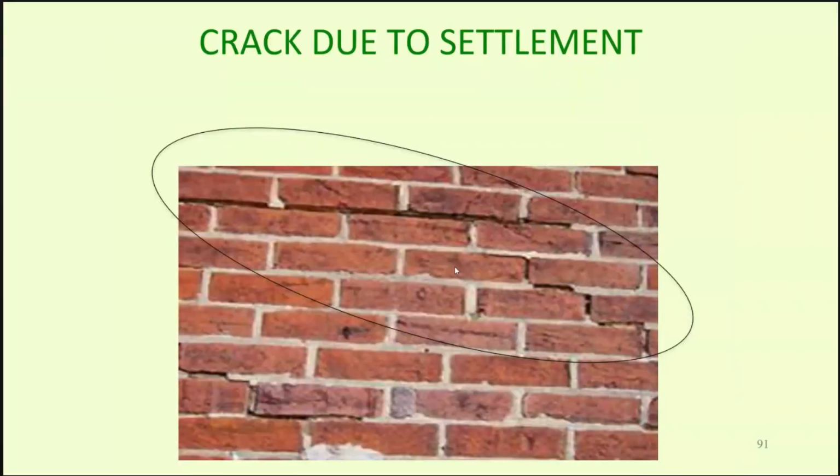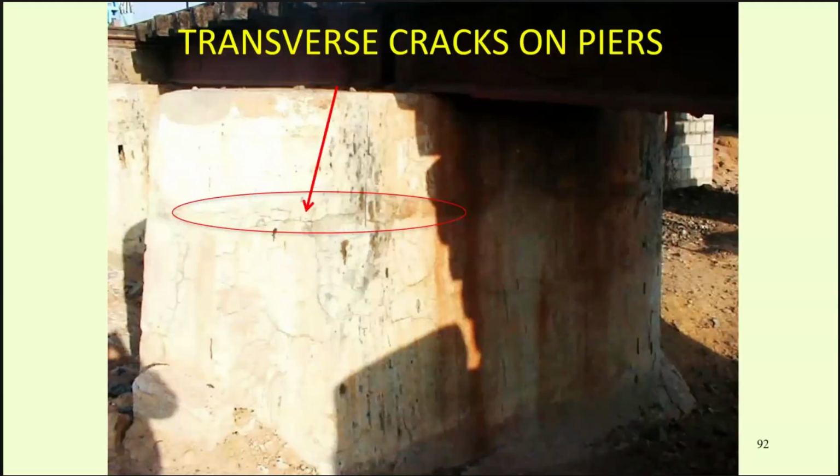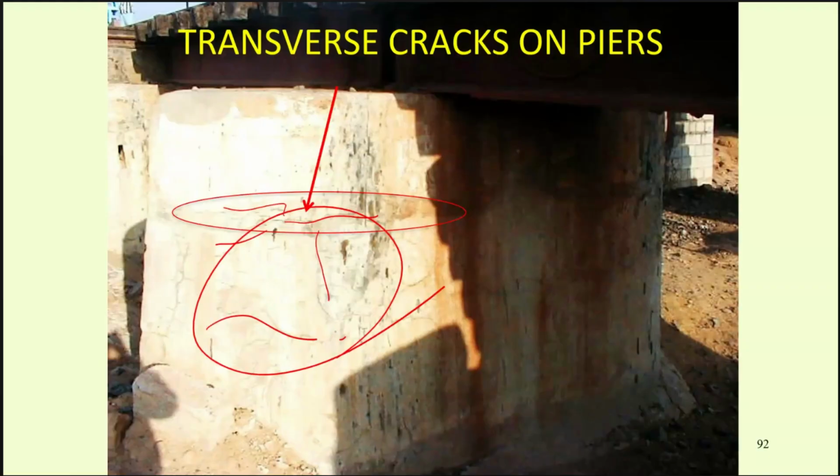Here you can see a zigzag crack pattern. This clearly indicates that something is moving at this end, which means the structure has started cracking. Likewise, in the substructure you have a lot of such crack patterns. That also indicates a poor condition of the structure. It is not going to fail immediately, but it is alerting you. You should see it and be alerted.